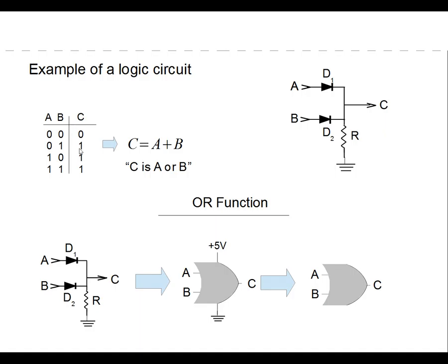And this is the truth table we just did, okay? And this is saying that C is equal to A or B. So C is equal to A or B, and that's what this circuit generates. So we actually have kind of an equivalency here. We can talk about this truth table, which is the OR. We can talk about the Boolean algebra here, which is the OR. We can talk about the circuit, which produces that OR function under proper given assumptions, or we can talk about the symbol that produces the OR function.